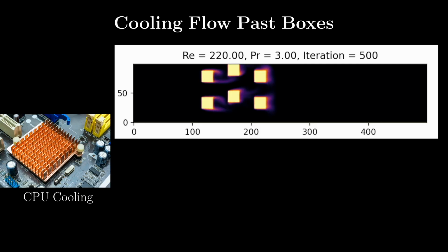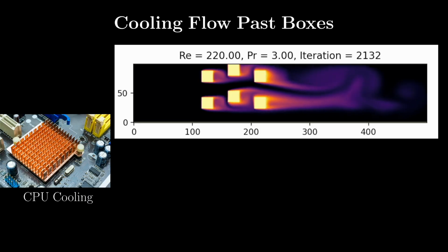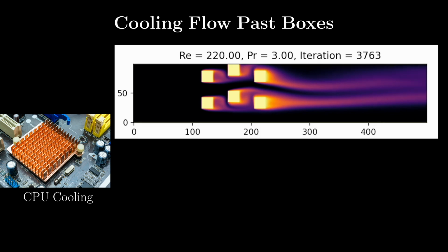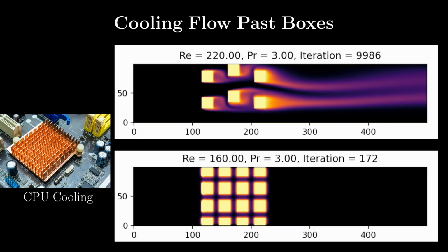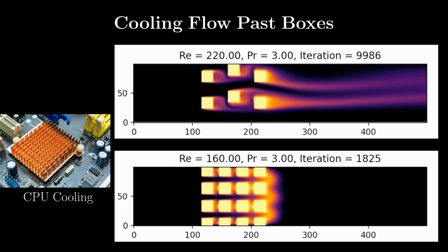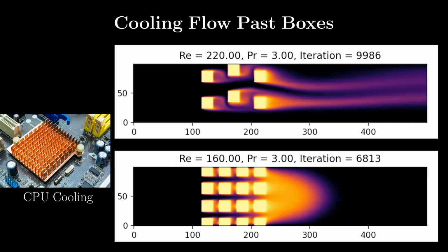By replacing cylinders with rectangular blocks, we can simulate the thermal behavior of CPU heatsink fins. With a small number of fins, fluid flows freely between them, creating distinct wakes similar to the cylinder arrays. However, as we pack the fins closer together, the physics changes. The increased surface area creates more drag, forcing the air into a smoother parabolic velocity profile, similar to flow through a narrow pipe.